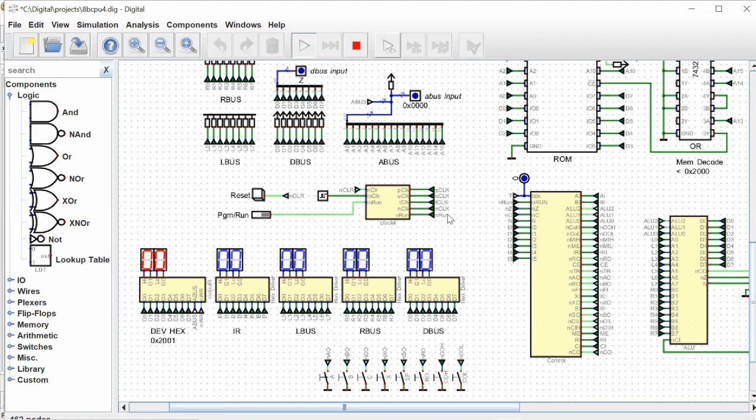So we can see again, our clock signals don't start up in a valid state, so we need to hit the reset. But we see our oscillator is in fact oscillating. I'm going to hit the reset and we should start running. And there we are, we're running through our test harness now, and we can see that cycling through. We can peek in on our running computer, our instructions and what's going on on the bus.